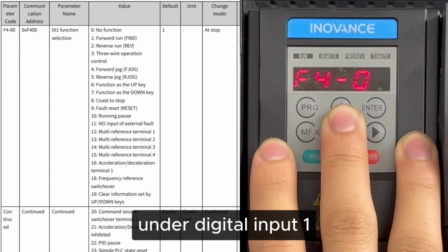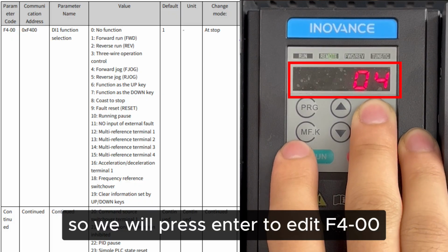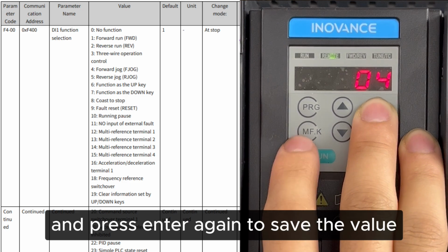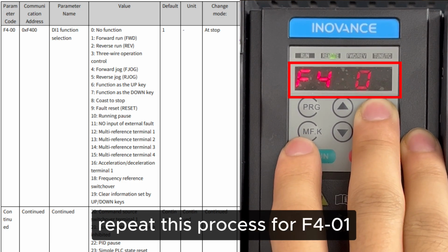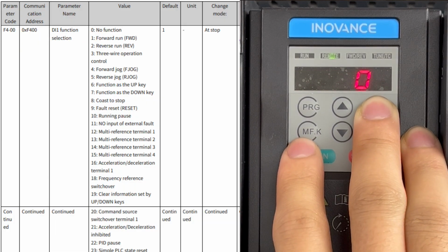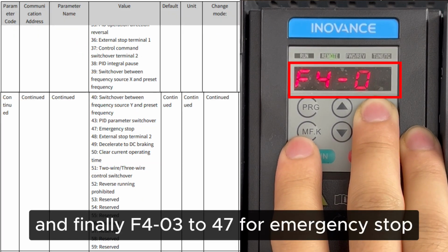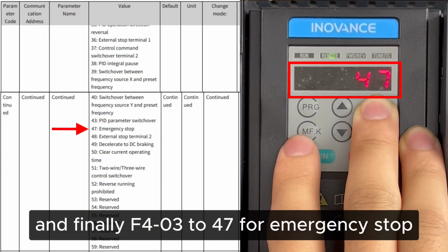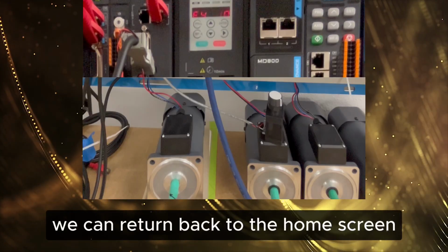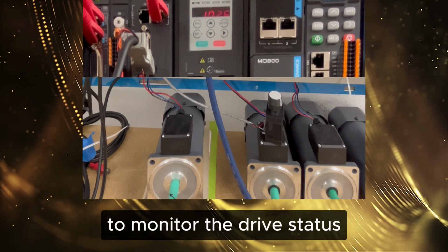Under digital input 1, we will set it to the forward jog function. So we will press Enter to edit F4-00, modify the value to 4, and press Enter again to save the value. Repeat this process for F4-01, which we will set to 1 for forward run, F4-02, which is set to 2 for reverse run, and finally, F4-03 to 47 for emergency stop. Once we have saved all of these values, we can return back to the home screen by pressing the Program button twice to monitor the drive status.